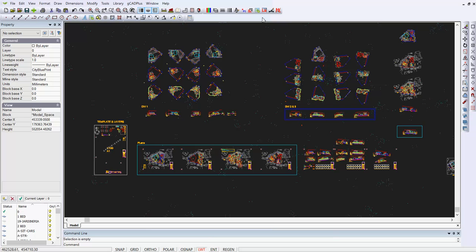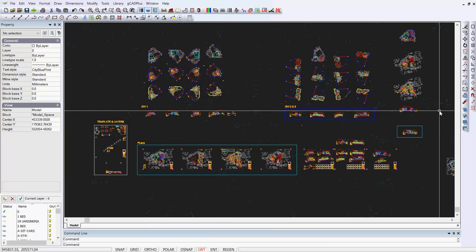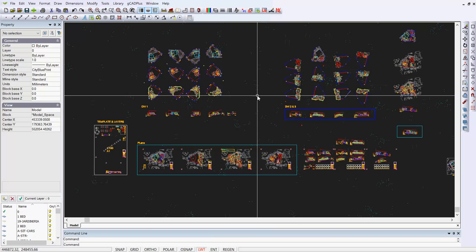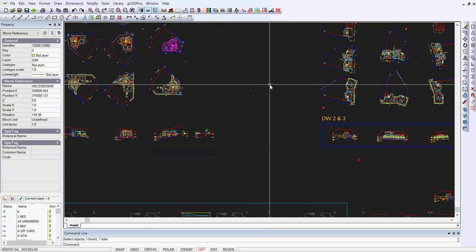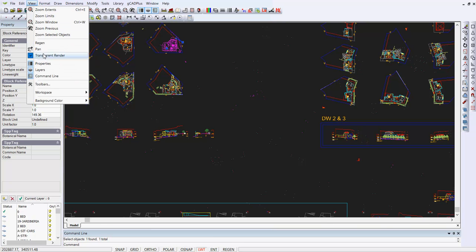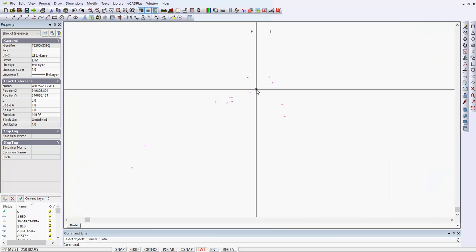In fact, if you look at the blocks list, if we go to the top here, you'll see all of these anonymous blocks, many of them empty. You may be able to see lots of fine blue dots, and if I click on these light blue dots, which I imagine will be quite difficult for you to see, let me just change the background to white, and these are the tiny dots.